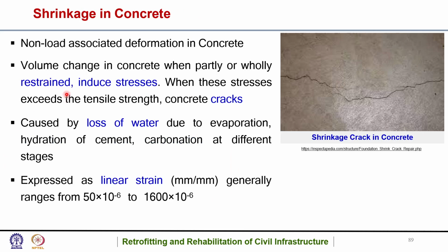Now let us go to the next topic, which is shrinkage in concrete. That is the non-load associated deformation in concrete. The volume change in concrete, when partly or wholly restrained, induces stresses. When these stresses exceed the tensile strength, then the concrete cracks.